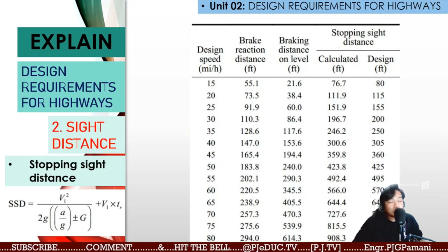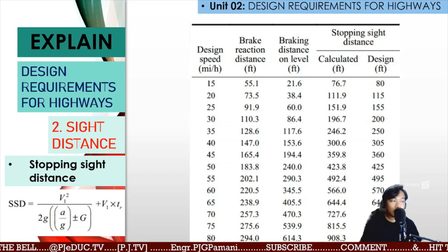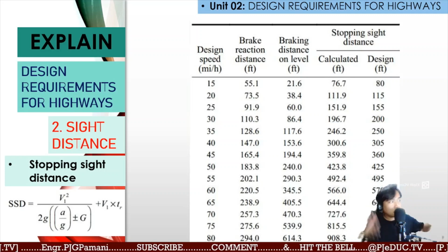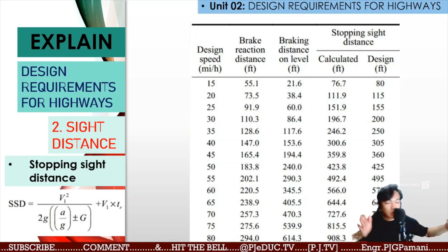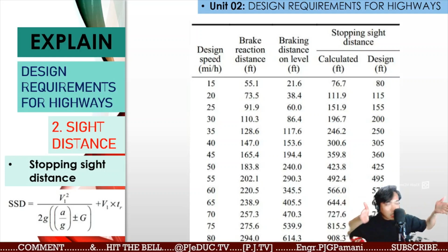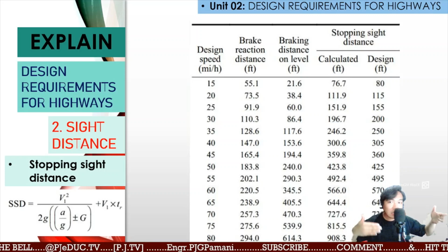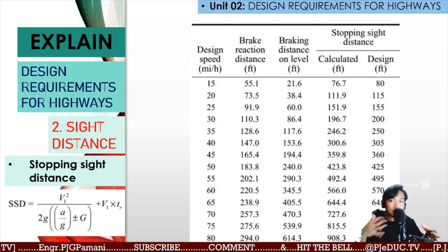So if your initial speed or design speed on that roadway is, let's just say, an expressway at flat of 80 miles per hour, the brake reaction distance should be 294 feet before the intersection or before the curvature. So at 294 feet, the movement of your vehicle should already be slowing down, no? And you're at 80 miles per hour. Beyond that, you will then expect accidents.